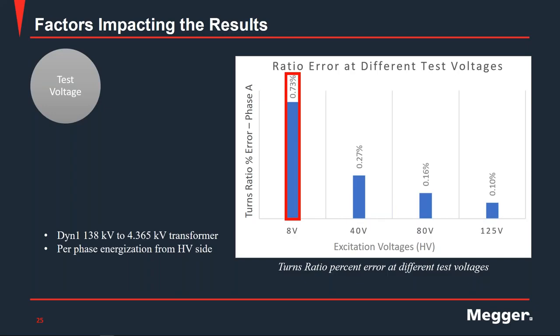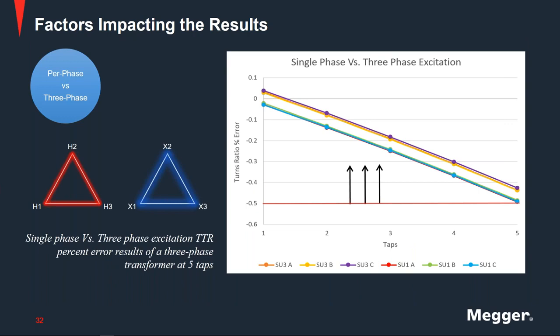Look, if you can induce voltage on the other side, and also going back to Ken's points during the presentation, doing single phase versus three-phase excitation is also important, as three-phase excitation on a three-phase transformer will be a more accurate measurement.